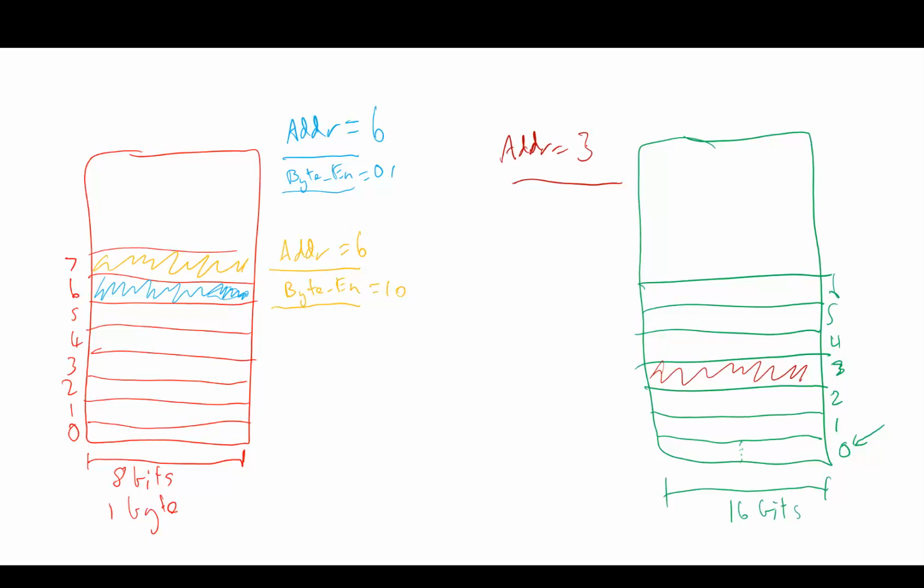Now, if you were just writing a byte, the lower byte, your address would be 3, and your upper byte, because it's active low, will be a 1, and the lower byte would be a 0. So that's activating this lower byte in this address in the SRAM chip.